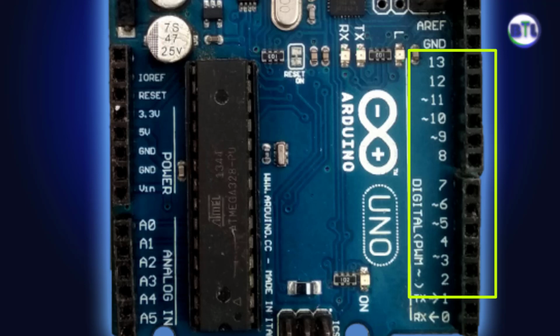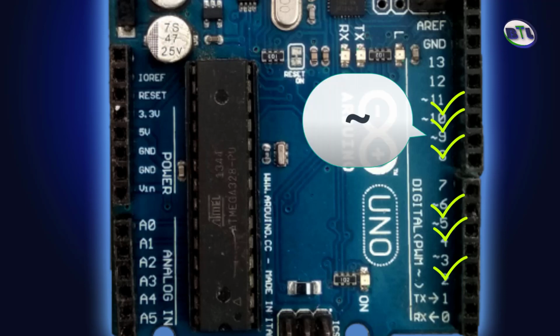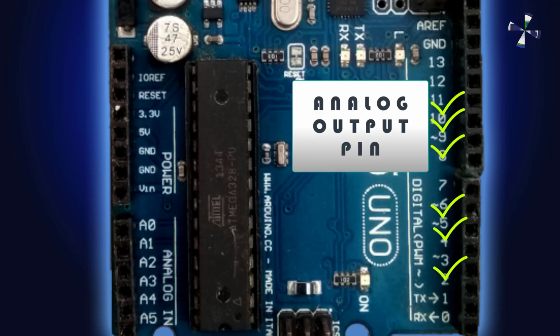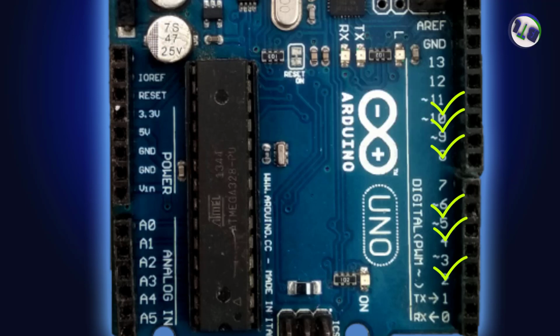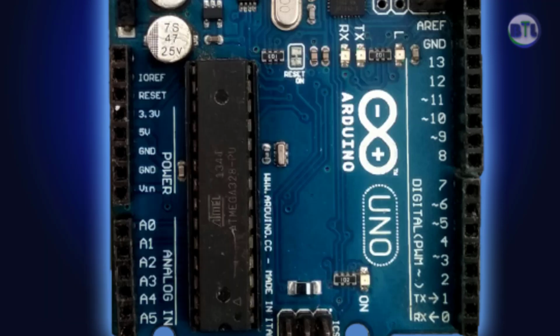We can see some of the pins, that is 3, 5, 6 and 9, 10, 11, with the tilde symbols. These can be used as analog output pins. Pins with tilde symbols can be used to output PWM square waves, that is pulse width modulation square waves.